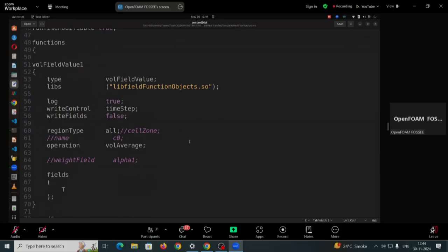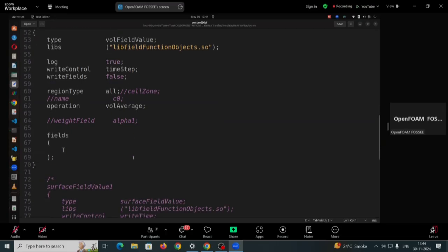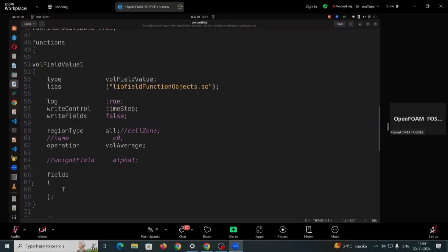So whenever you are running a simulation and you want to know if your simulation is converging or not, like in the first case, we were only able to somehow capture the interface temperature, because for some reason with CHT, the volume averaging was not working. Okay. This is not CHT. This is buoyantSimpleFoam. And over here, I am able to use the volume field function and extract the average temperature inside the complete region, and I'm able to plot this. So with this, if I plot it, I will get the temperature, how it is increasing. So this is something that you can add.